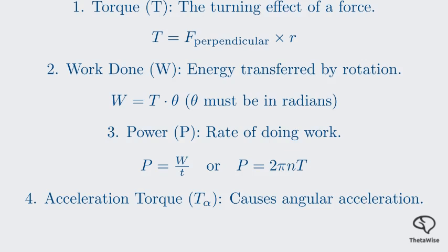Finally, we introduced acceleration torque, which causes a change in rotational speed, and its formula, T alpha equals moment of inertia I times angular acceleration alpha. You are now equipped to define, calculate, and apply these key concepts of torque, work, and power to various rotational problems.